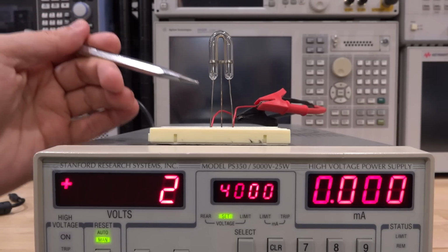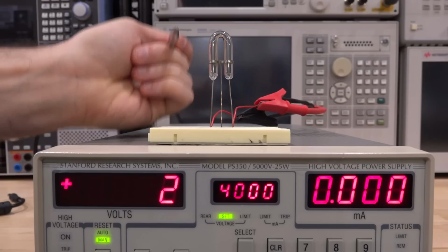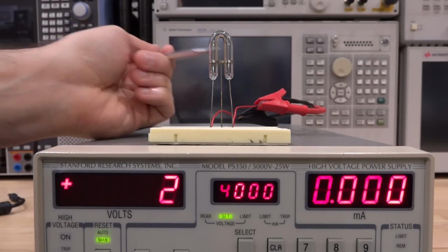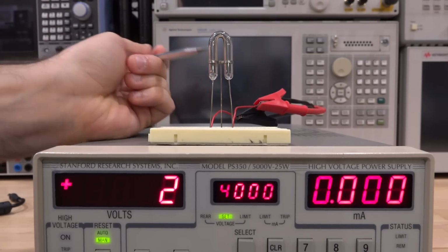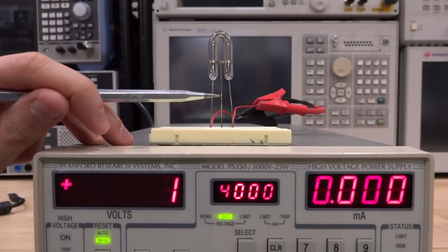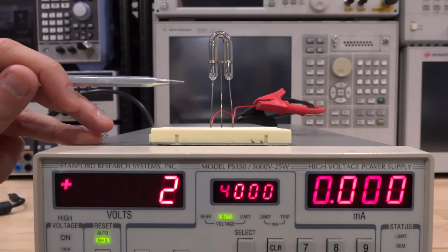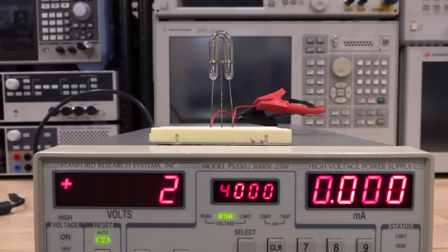So here at the top, I have a strobe light, and these strobe tubes are intended to produce a lot of light by passing current through an ionized gas. Now if you look, almost all of them have 3 terminals. There are the main 2 terminals on each side, that's where the current flows, and there's a 3rd terminal sitting in the middle that doesn't go inside the tube, it just has a ring around the outside of the tube. And that's because you need some way to strike the tube so you can begin the flow of the current.